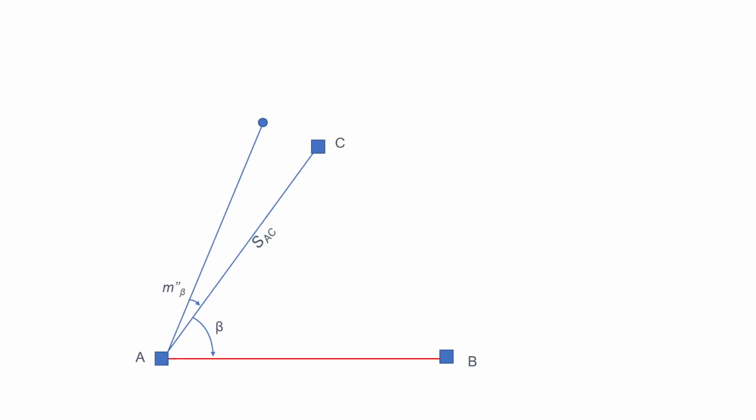Another method is here, you can see the tolerance and mistake of the setup of point C. While we set up the C1 point instead of C, we have two different parts of the mistake: a mistake caused by distance measurement and a mistake caused by angle measurement.